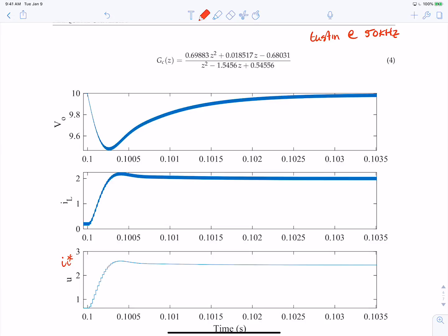You see this a lot in motor controllers. This is low power motor controls. You may be switching at, let's say, 50 kilohertz for a low inductance machine, or 75, or maybe 20, but your update rate for your controllers may be orders of magnitude smaller, or integer multiples smaller. So you may be updating at 10 kilohertz or 5 kilohertz for your current controller or for your torque command. So it really just depends on the application. Essentially, you have a multi-rate system.